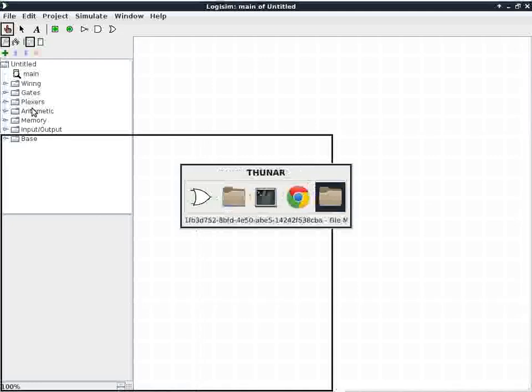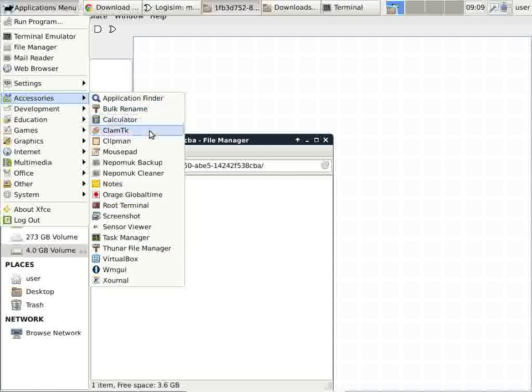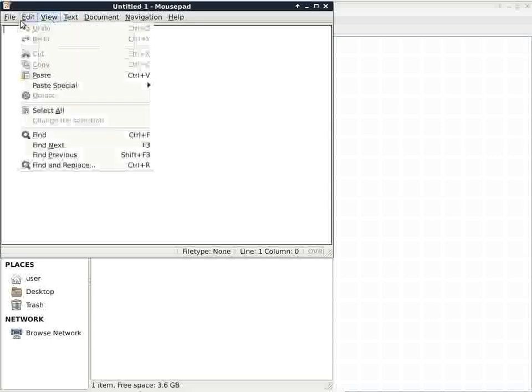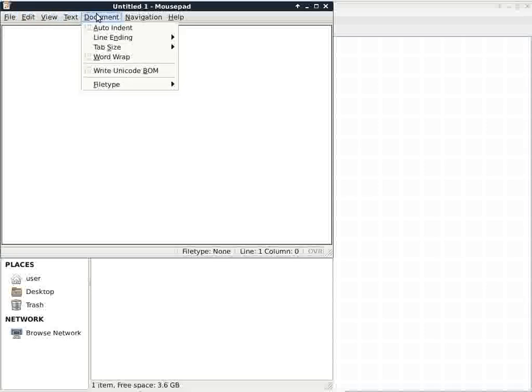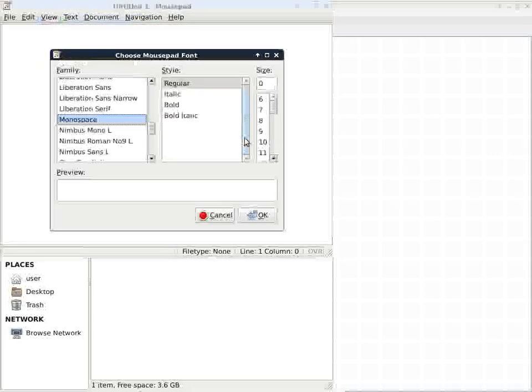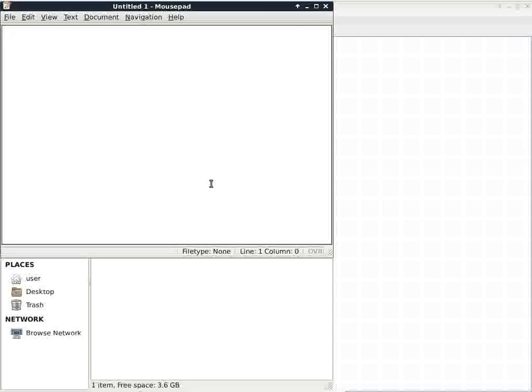Okay, now if you still remember what a half adder is, it performs the basic rule of adding. So I'm going to use an editor, kind of like a little whiteboard notepad thing here. And what I'll do is show you something that you should know already because we talked about it just 2 days ago. But I'm going to put it here just so that we get that part. Okay. So the part that you need to know is 0 plus 0 has a result of 0, and the carry is 0 as well.